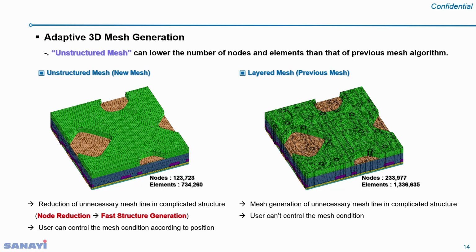In addition, depending on the simulation cases, the selection for used mesh should be different. By our simulation data results, it is recommended to select the layered method for a simple structure without a pattern or a bendable structure. And for a relatively complex structure, using the unstructured mesh is effective.